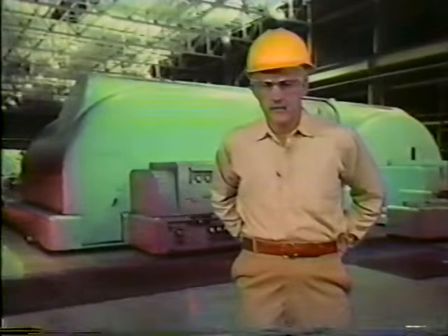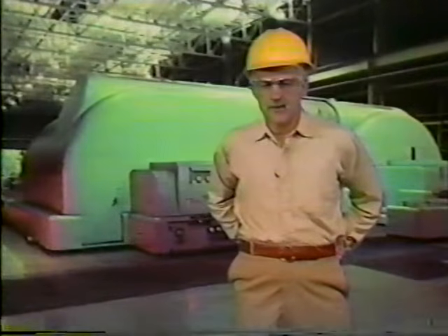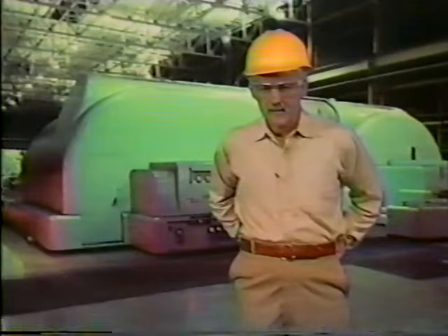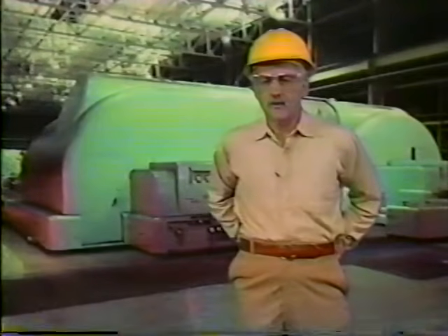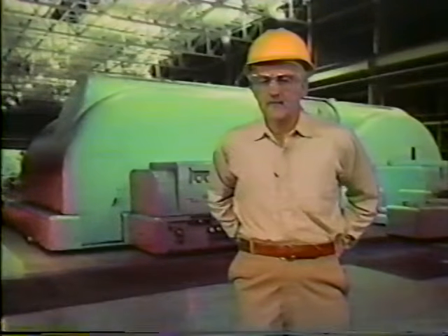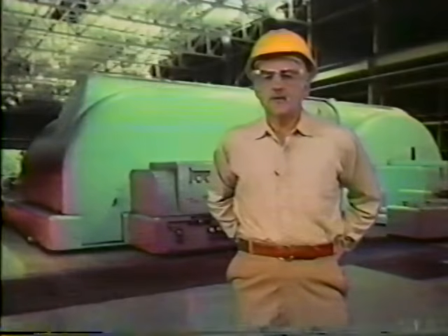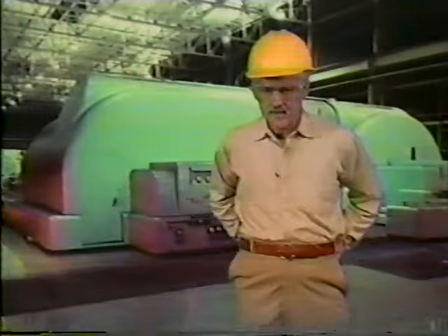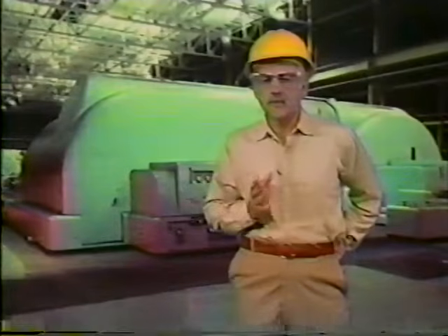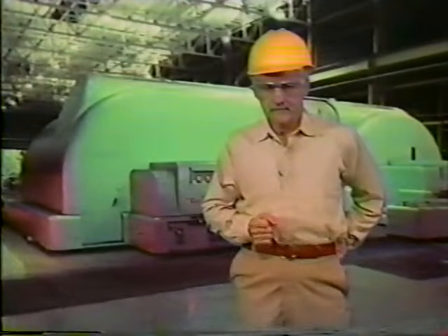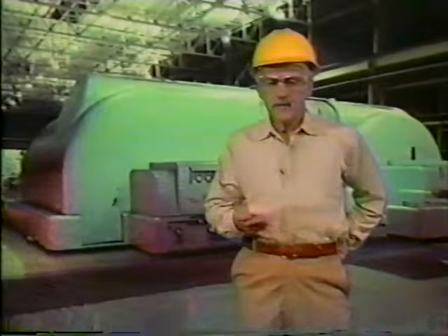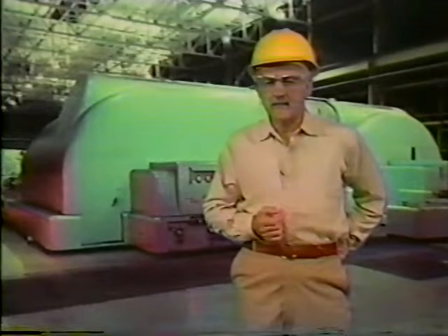Overheating is not the only problem caused by a turbine trip or shutdown. Another possible problem is overspeeding. We've already seen that during a load rejection, intercept valves prevent overspeeding. But during a turbine trip or shutdown, a different valve prevents overspeeding. This valve is called the emergency blowdown valve. To understand how the emergency blowdown valve functions, we need to look at a turbine in a little more detail and examine a condition that may cause overspeeding.